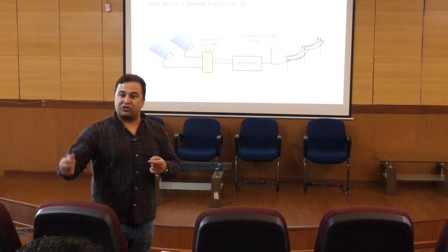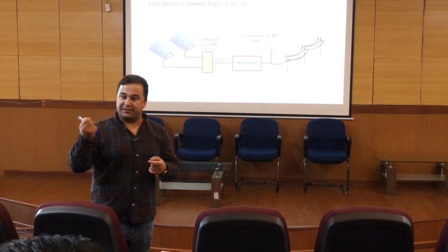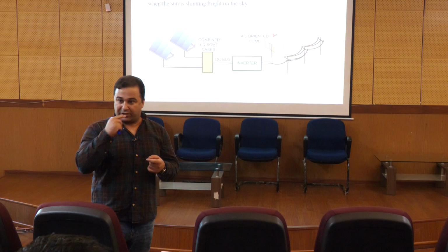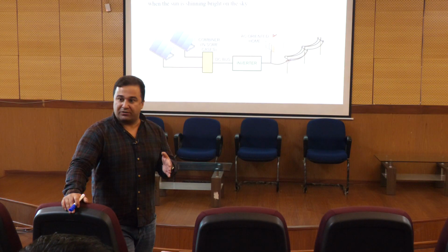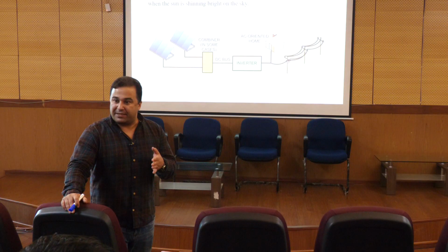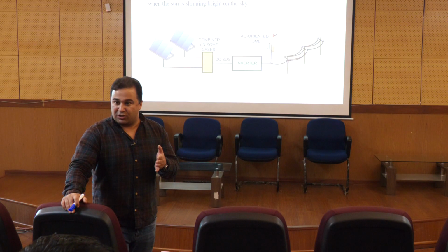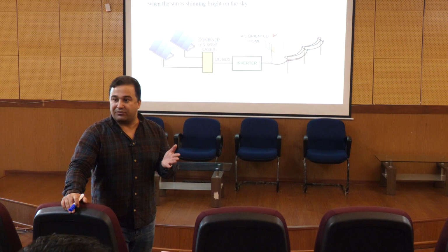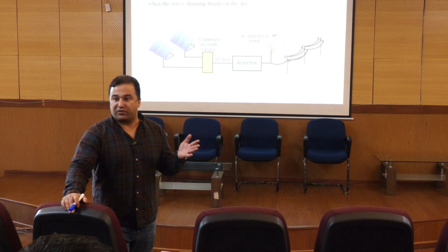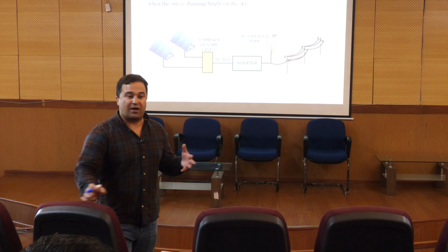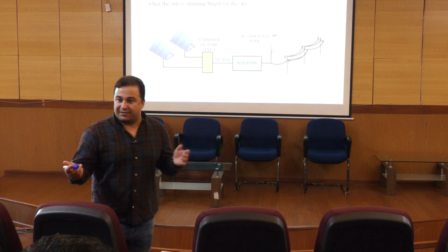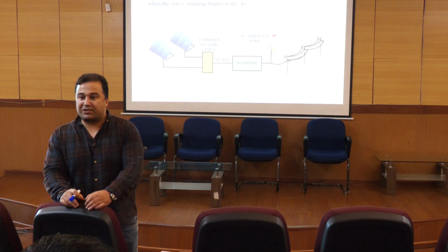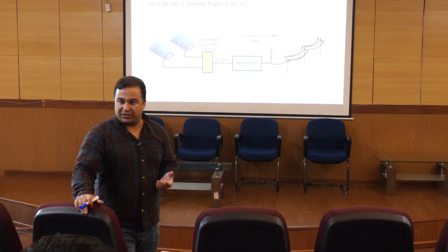Why? Because you have the reference from the grid. So when the grid is shut down, it means that you miss the reference, so your reference will be zero value. It means that the output voltage of the converter is zero. It doesn't matter that you have lots of sources. Your converter is like a zero value actually. The output voltage is like a diode converter. Okay, so it doesn't work.